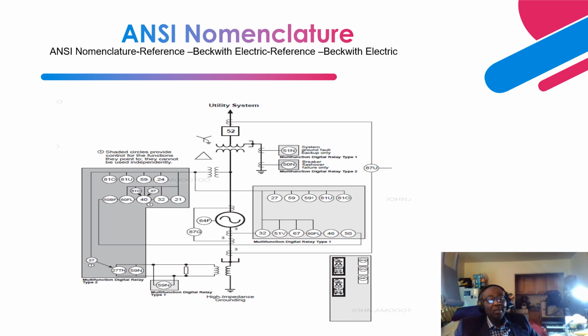So we need another relay to complement that protection. That is when the 27TN covers the remaining 5%. As a matter of fact, they set it in such a way that it overlaps. It covers about the last 10% of the neutral of the generator by creating an overlapping zone.